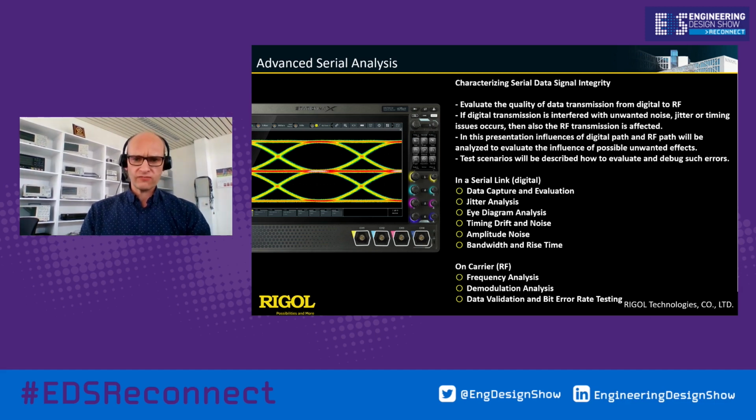Therefore, we want to focus first on the digital part: how to capture a digital signal, how to analyze a digital signal with the tools of jitter analysis and real-time analysis, to take notice of some timing drift, noise behavior and amplitude noise behavior, and then also discuss some bandwidth and rise time issues.